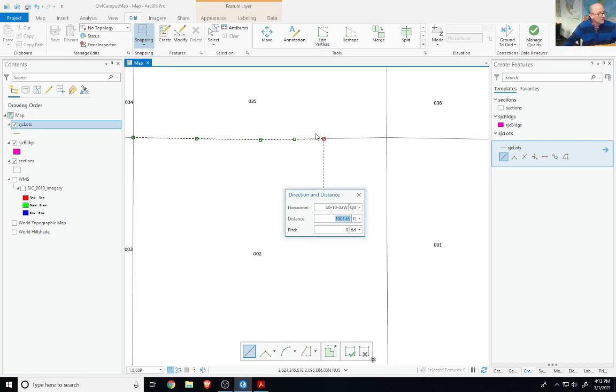On this particular one, on the far east boundary of this property, it's going south 0 degrees, so I just put a 0 and a dash. You do have to have that placeholder in there. It has to have all 3 in there. Otherwise, it's going to assume that if there's less than 3, the first one is the degrees. So just keep that in mind.